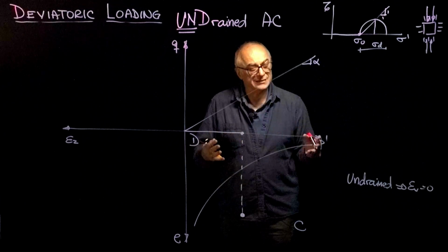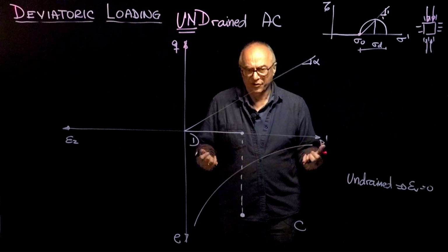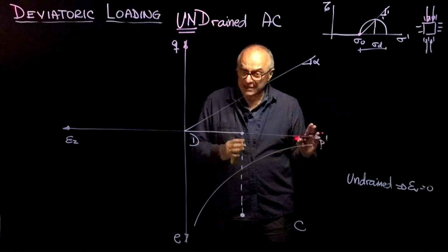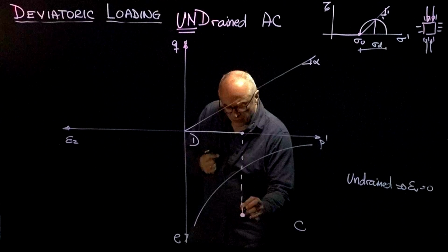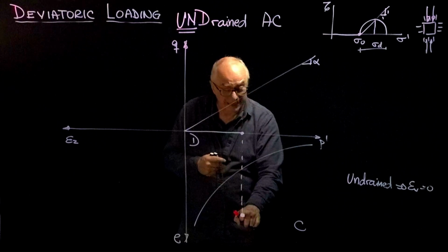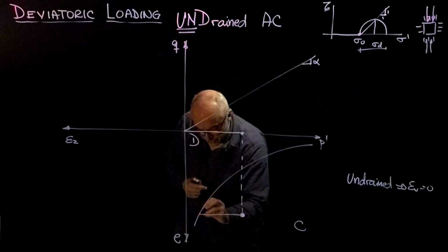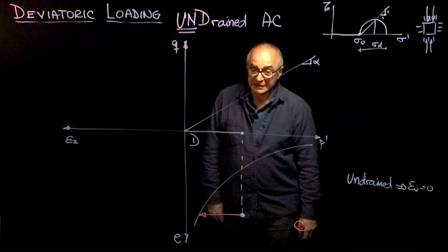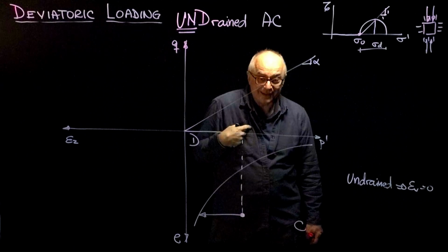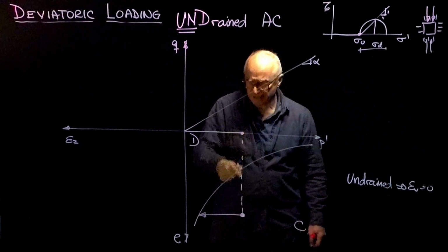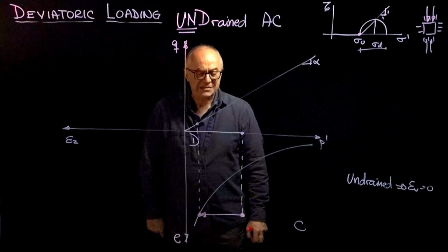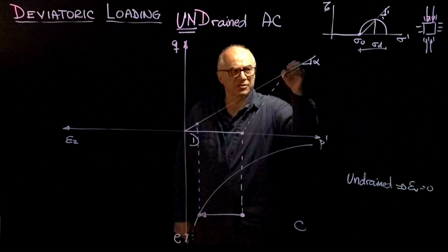By the way, there are important unstated assumptions there, like, for example, that particles are perfectly rigid and that the water is perfectly rigid. Under those assumptions, what we know is that this soil will go to failure while we're loading it, but the only way that soil can go to failure at constant void ratio is to move in this direction. So this is where the soil will find failure. You think you were loading the soil in this direction. Internally, the soil is not feeling that stress because this point here now must have a projection on that point there. And so what happened is you were loading the soil in this direction at a 45-degree angle.